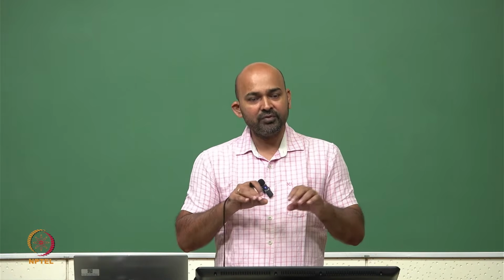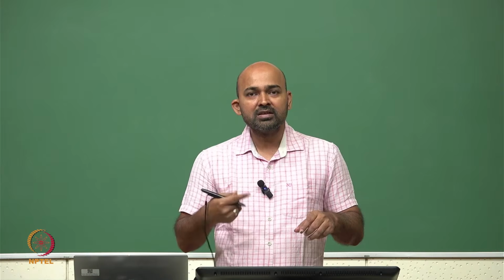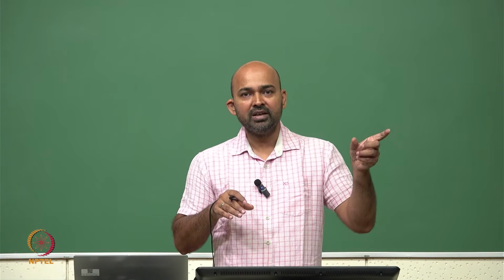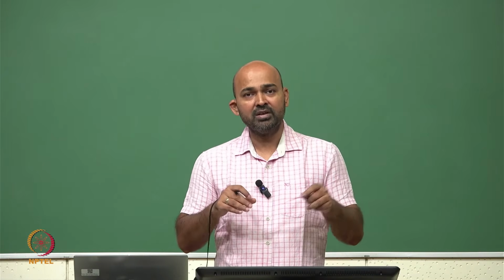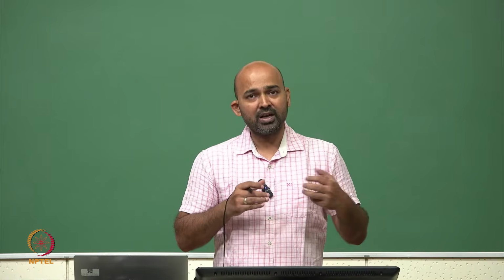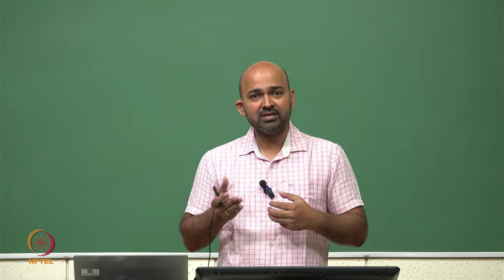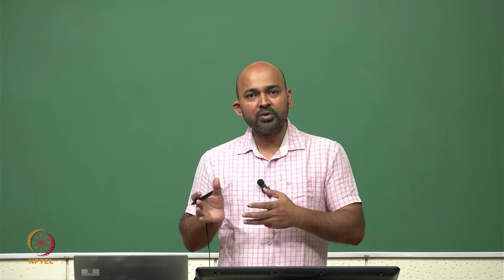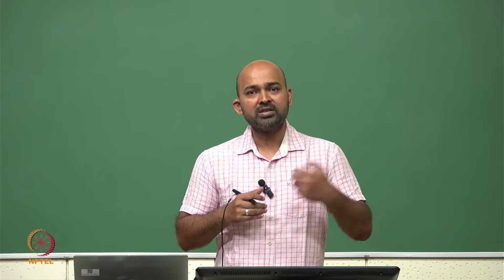The same URL we can specify in the schematic, and when we simulate this circuit, automatically spice will look over the internet and find the model on that path which we have given and take the spice model directly from that. The limitation of this method is when you are doing the simulation, your computer should be connected to the internet, otherwise it will not be able to fetch that model.